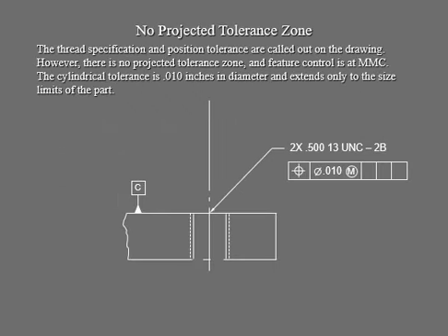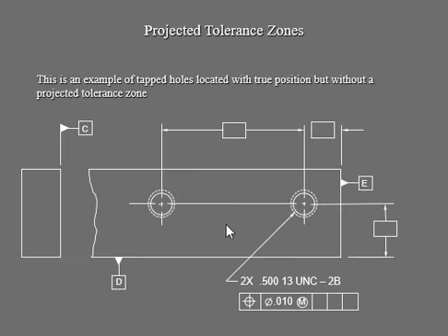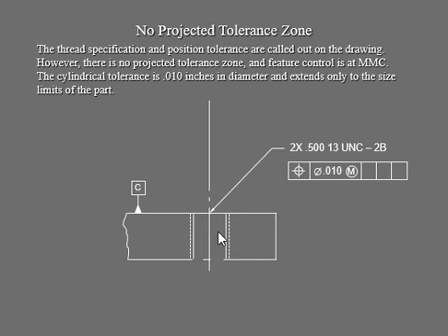And then let's go. Our strategy is to come up with the projected tolerance zone. And your feature control frame, of course, has the modifier M, this little M telling you the maximum material condition. So your cylindrical tolerance, we're going to put it into this view, which is here. Now we're going to look at this from the side view, so you can see the cylinder very clearly. So your cylindrical tolerance is 0.10.